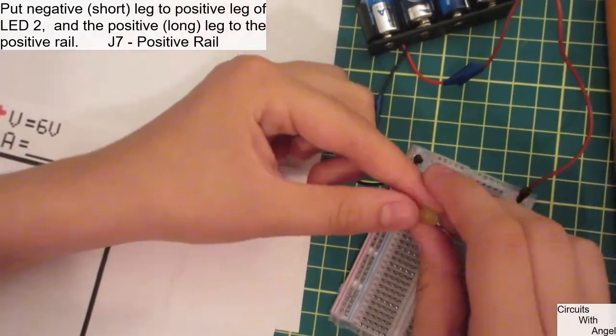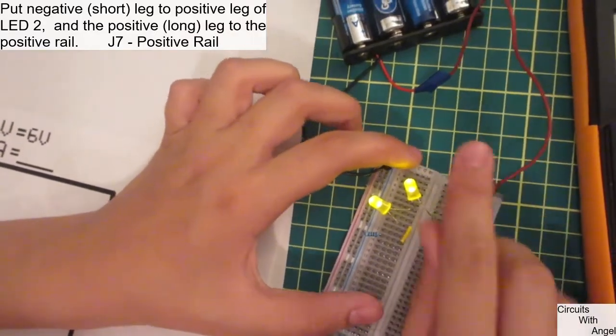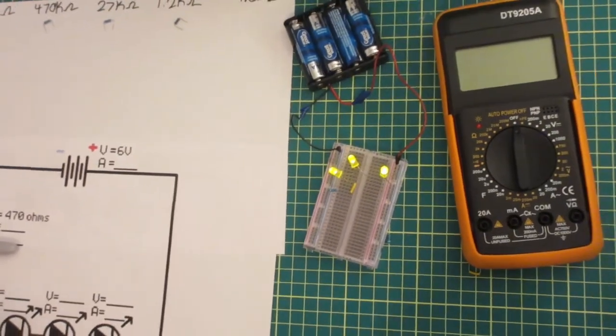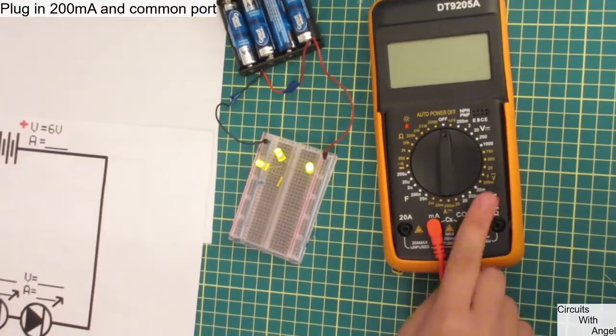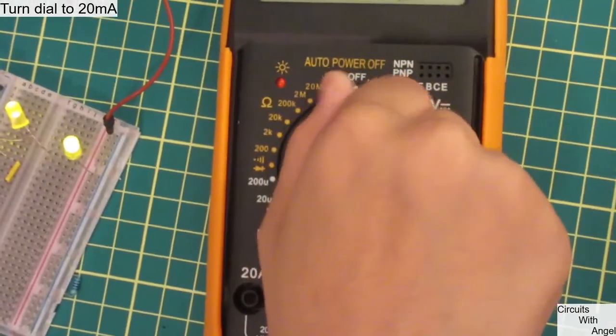And for our third LED, LED 3, we take its negative leg and put it to the positive leg of LED 2, and we take LED 3's positive leg and we put it into the positive rail. If you don't understand anything, just back up and you can watch it all over again.